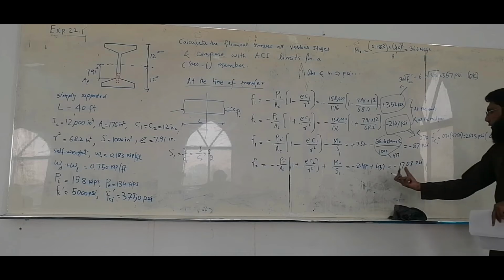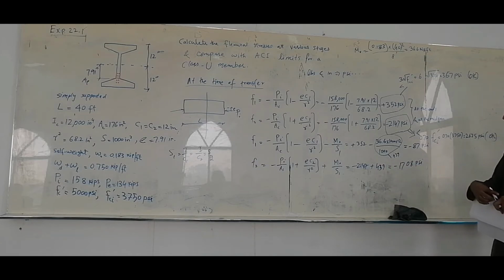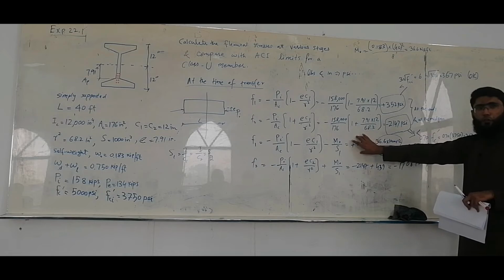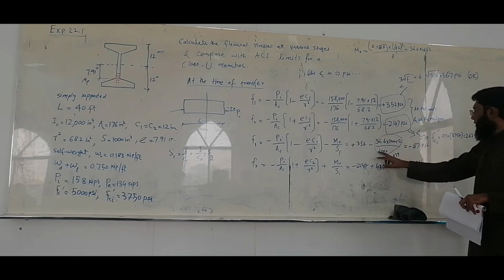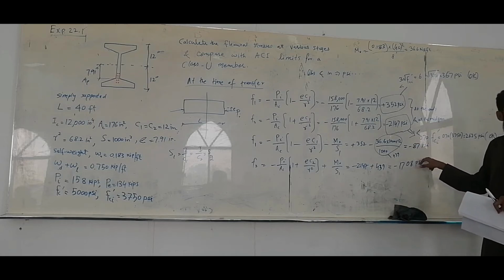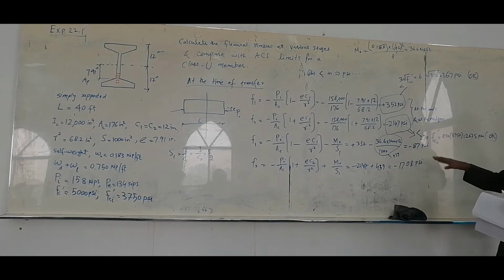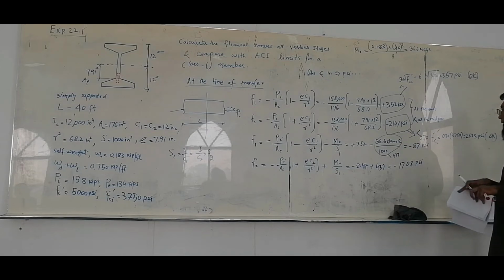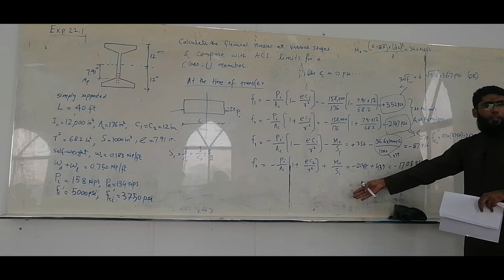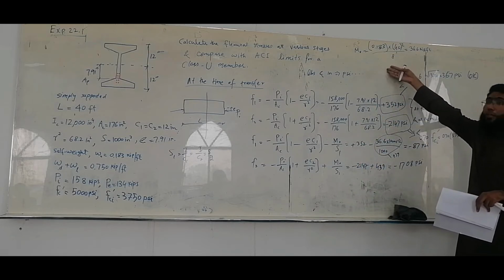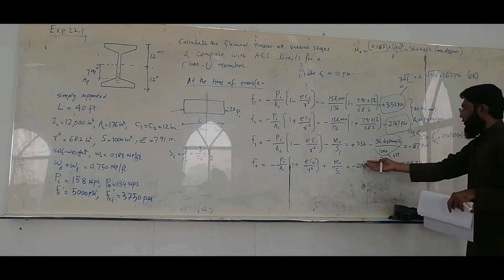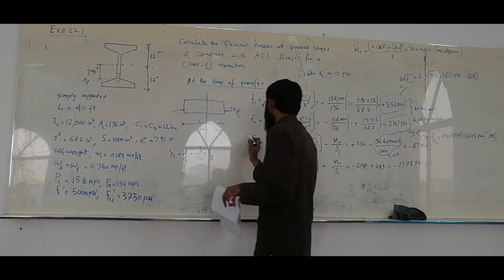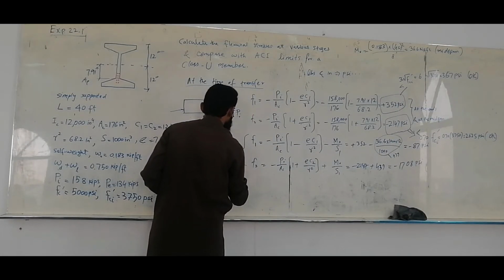Over here, we have a tensile stress due to the prestressing forces at the top, and a compressive stress due to the self weight, which ultimately becomes a net compressive stress. So there is no tension anywhere in the cross section at the midspan. These are at the midspan because this moment value, M naught, is at the midspan, so these stresses are also calculated at the midspan.